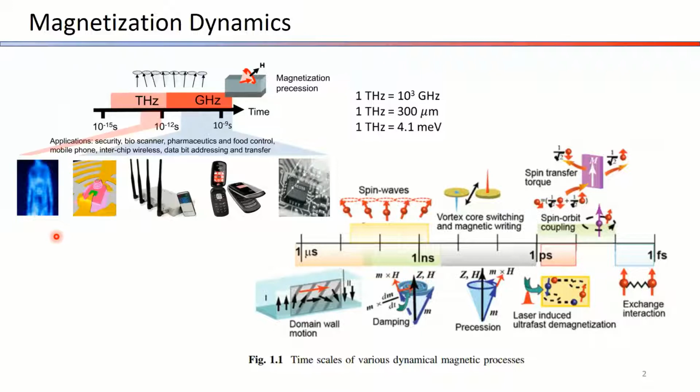There are unique properties of the radiation that make it an interesting technique in pharmaceutical and security applications also. Detection and imaging of drugs, explosives and bioagents, non-destructive and non-invasive testing and inspection, pharmaceutical and foodstuff quality control, and medical diagnostics are other applications related to terahertz spectroscopy. Using terahertz as a carrier in secure communication has led to some advantages, namely small antenna size and large information bandwidth. Lower scattering and much greater penetration through aerosols and clouds have made the terahertz signal more favorable compared with IR and optical wavelengths for communications.